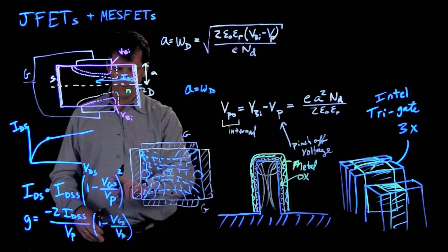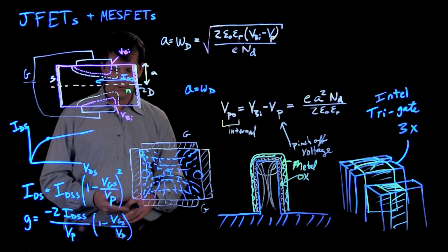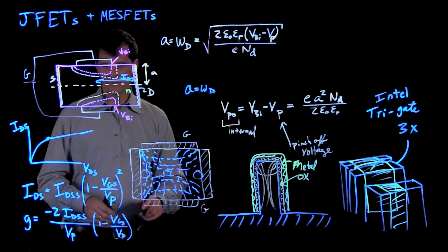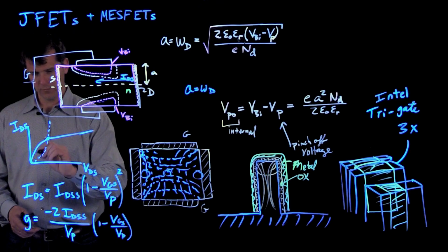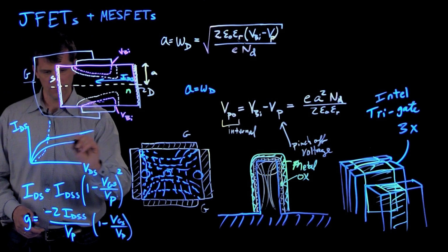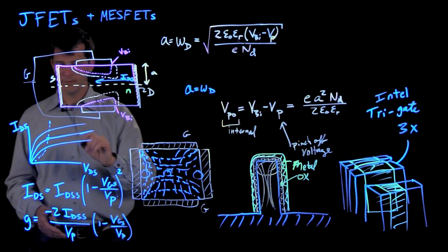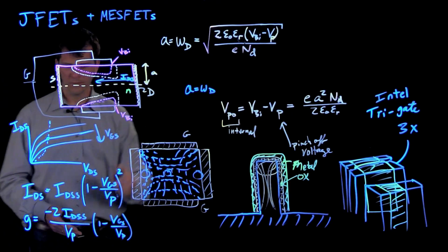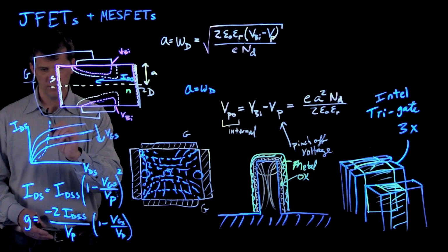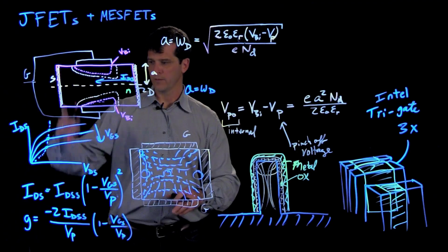And then we have a similar expression to MOSFETs, a squared function of the gate source voltage, which defines a parabola for a family of curves having different gate source voltages. So our increasing V gate source goes this way, and these rollover points or saturation points are going to describe a parabola.